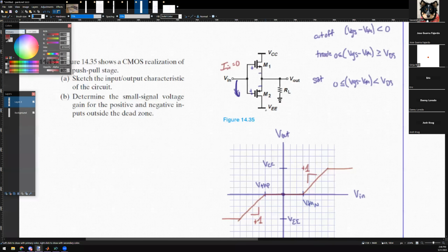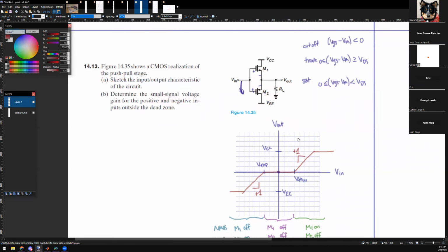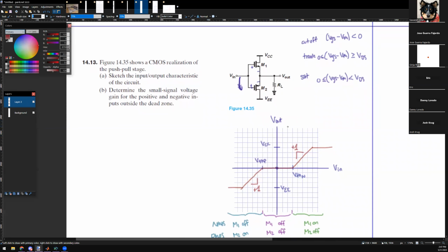Yeah, it's very common, but you see a problem in the center: your audio is going to sound like absolute garbage. So there are ways to fix this. Typically, what you do is you put a diode or so here. Can you also have the configuration with only a source follower rather than a push-pull stage? You mean only have one and a resistor for the other? Yes, but your swing is smaller. This one, you see how you almost have rail to rail swing.